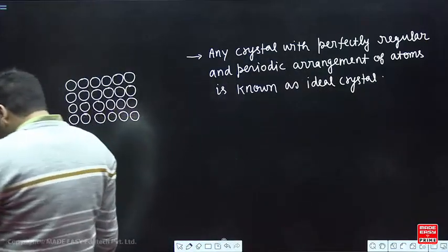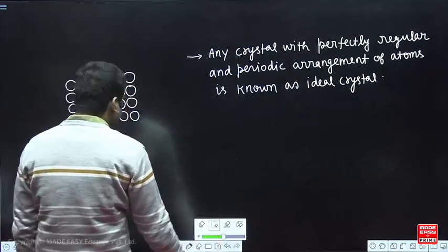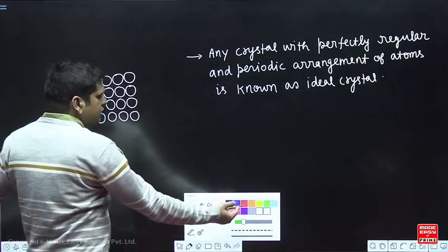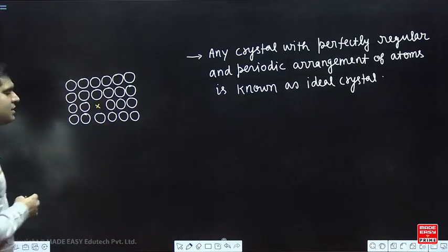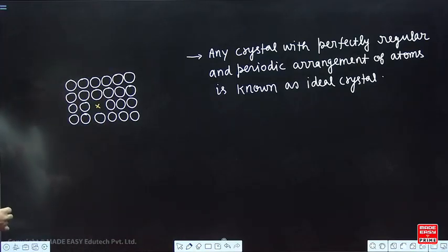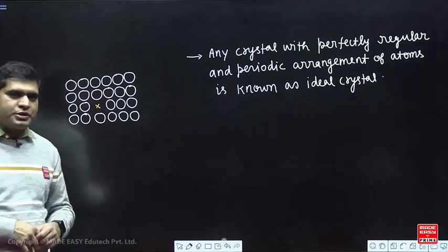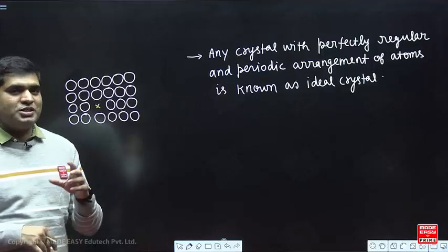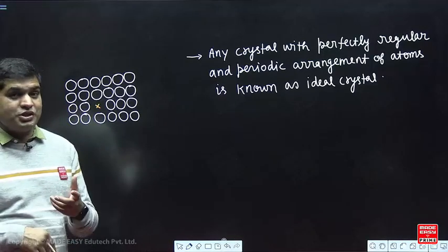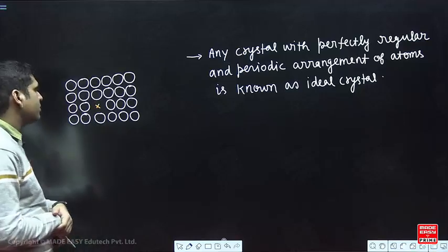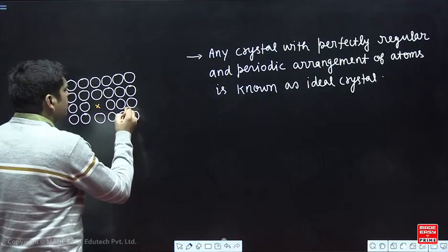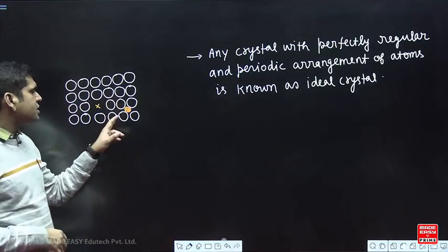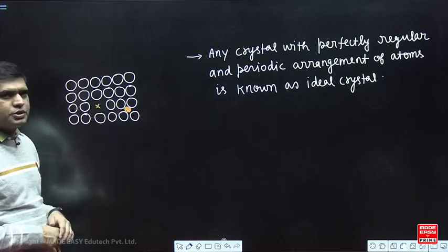Right? But in real crystals there are certain problems. Let us suppose one atom is missing. One atom is not available at its lattice site. So we cannot say that it is a non-crystalline material. We will be saying that it is a material with certain defect. But at this point periodic order is not followed. So there is a disturbance in periodicity. There may be a possibility that some impurity is there at the interstitial site, or some other material atom is there substituting.